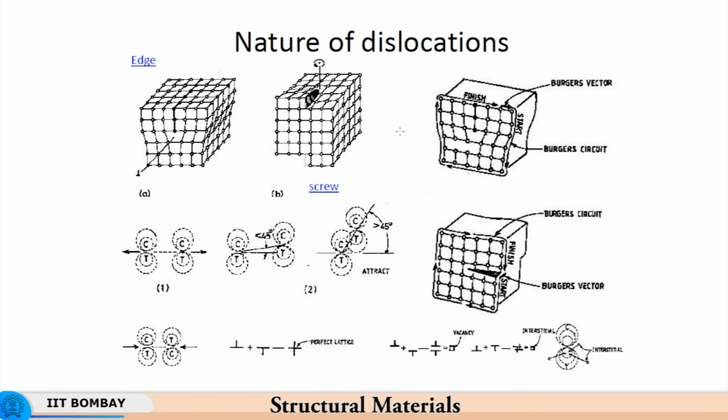Okay, right. Now, if you have dislocations where unlike stress fields come together. Here we had like stress fields coming together at different angles. Now, let us see what happens when unlike stress fields come together. Compression, tension, the plane is the same, but the dislocations with opposite directions come together.